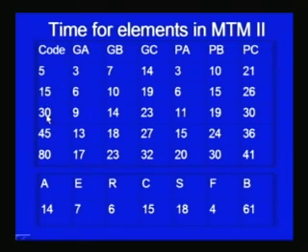If it is in the range of 15 to 30 centimeter, it is given code 30, and for a distance to be travelled by the hand while performing the get or the put of 30 to 45 centimeter, code 45 is given, and similarly for a distance more than 45 and up to 80, it is given code 80.